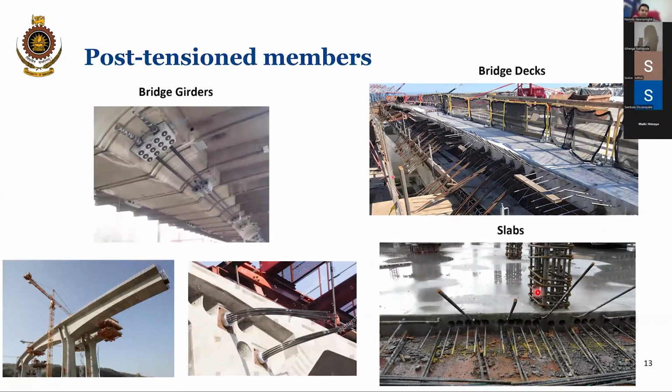So one thing is it reduces the cost of the formwork, and you can have more space between two columns, aesthetically better, rentable space is higher. And also, the floor-to-floor height can be reduced because there is no beam. So the additional stiffness that is not given by the beam is provided through this post-tension steel.